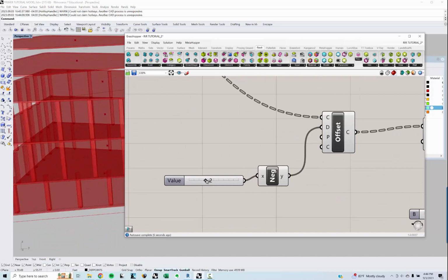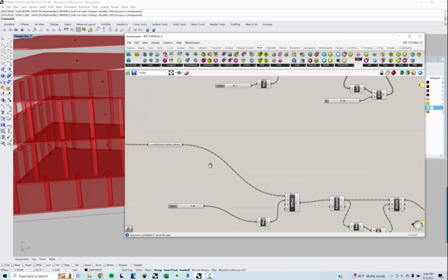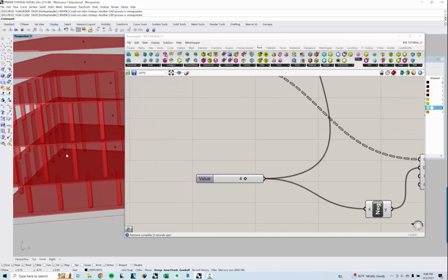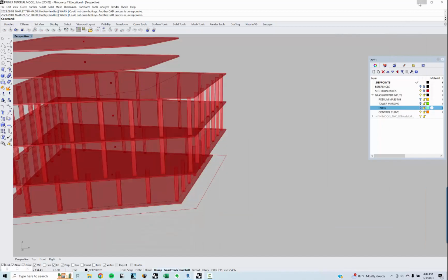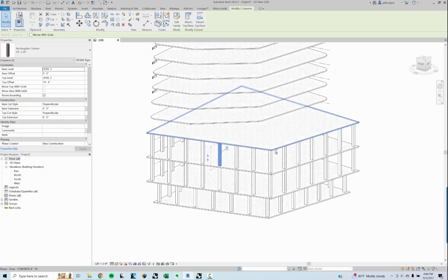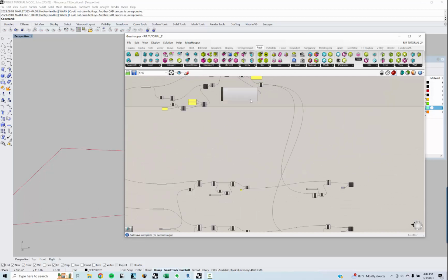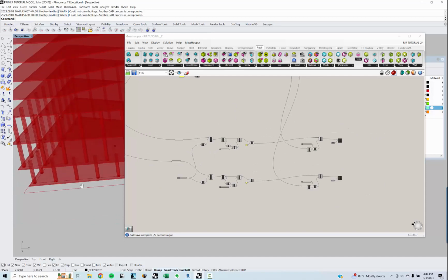And you know, if it's too close to the facade, we can change the offset. So you know what I'm going to do, just unify these so that they're pulling from the same place so I don't have two different sliders. But this will adjust the setback from here, and you can see it in Rhino updating as I do that. And then if I close this out, you'll actually see it in here, all my Revit columns. Okay, so that's it for the system families. I'm going to show you next how to do a different type of geometry creation using Rhino.Inside.